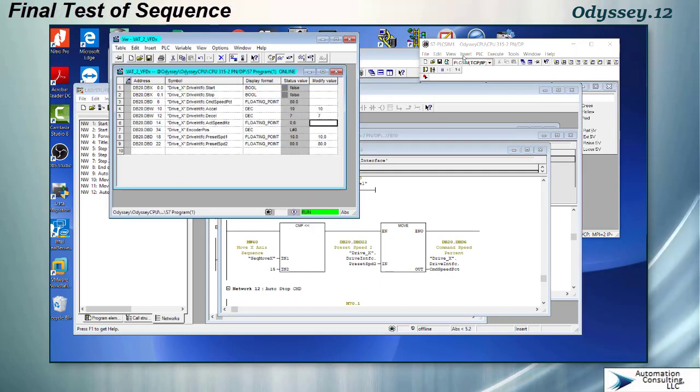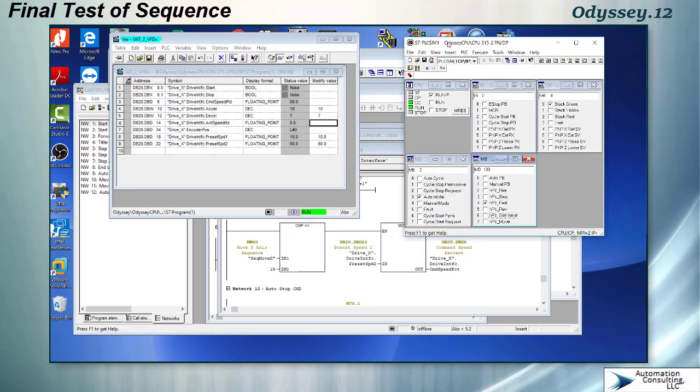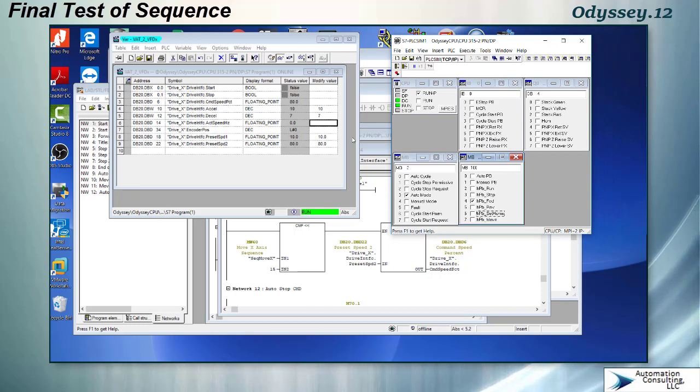So let's go ahead and run this, and you'll see how much quicker this stops. So I've already set my home position. I'll do a move. You can see it ramps up to full speed pretty quickly. When we hit our 4500, you will see this command speed percentage go down to 10. And you can see the actual speed is quite slow here. And then we stop.